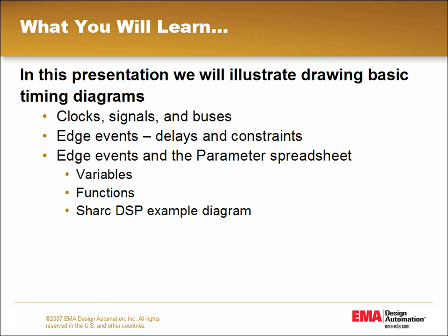This part of the presentation will illustrate drawing basic timing diagrams in TimingDesigner. We will cover clocks, signals, and buses, followed by edge events, which will include delays and constraints. And lastly, we will go over edge events and the parameter spreadsheet, where we will look at variables, functions, and an example diagram of a Shark DSP processor.